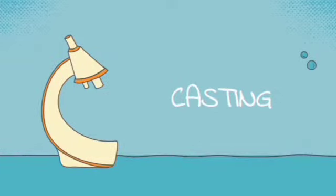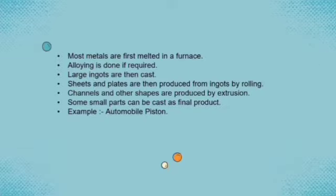The first method is casting. For casting, most metals are first melted in a furnace. Alloying is done if required. Large ingots are then cast. Sheets and plates are then produced from ingots by rolling. Channels and other shapes are produced by extrusion. Some small parts can be cast as a final product, for example an automobile piston.